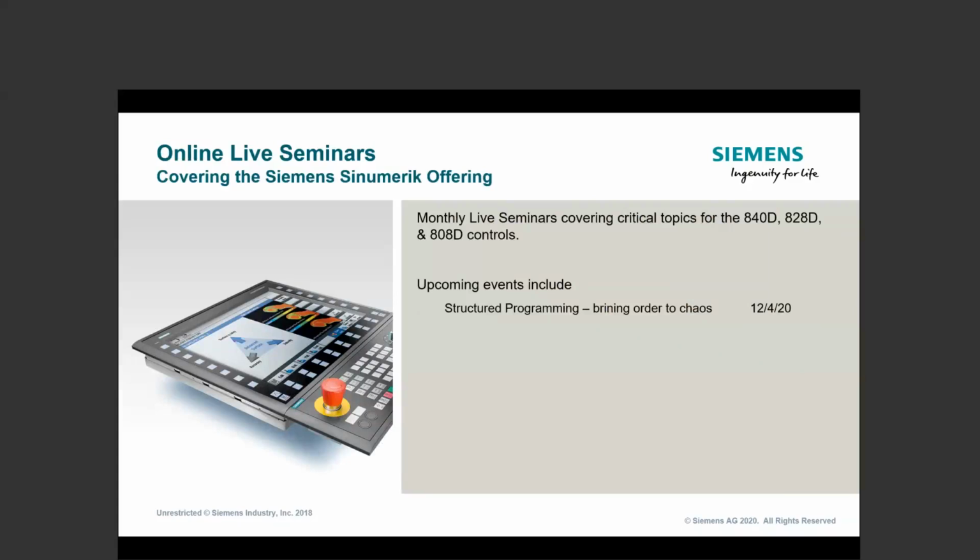You're not going to have a guest host today. But our next one coming up in December is going to go into the world of structured programming, which is pretty cool. If you don't know what the term structured programming is referring to, it's basically using variable-based programming to create intelligence in your part program. So if you're jumping from mains to subs and back to mains, the part program will always know where you were last at. If a program is aborted midstream, you can always start the program from line 1.